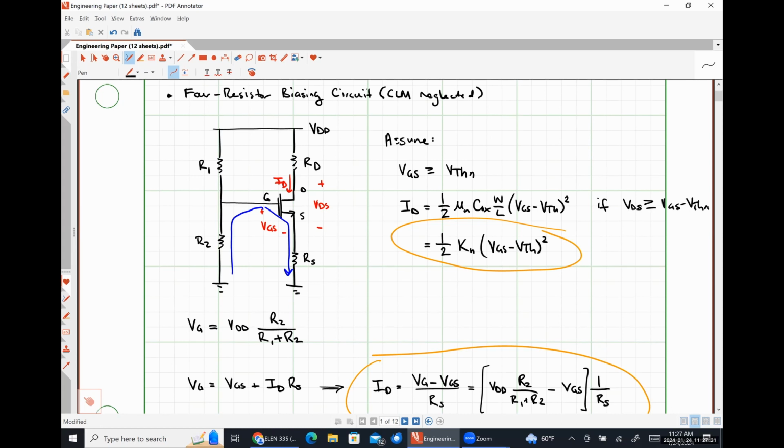No, that's not an equal. That's just a poorly written greater than or equal to VTH. Yeah. Nope, sorry. Greater than or equal to. So we need the device to be capable of conduction. And then in saturation mode, we know that VDS is greater than VGS minus VTH, which gives us this drain current equation.